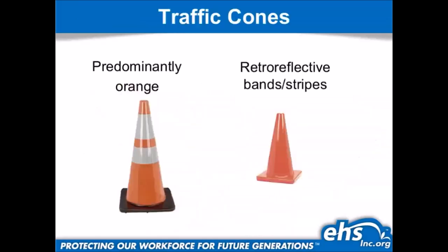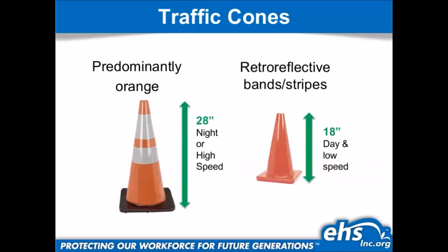Cones, okay, traffic cones. Now, most of the times when I get to this slide, the guys will tell me, yeah, well, all we use is those 28-inch cones. Again, all I'm letting you know is what the CAMUTCD says. Your local policies are going to be different than what the CAMUTCD says. Nowadays, if you drive through the majority of the cities, all you're going to find are the 28-inch cones. And that's good. You want cones that can be seen at a distance. And if you're leaving them out at night, they better be retroreflective, right? They have to be seen.